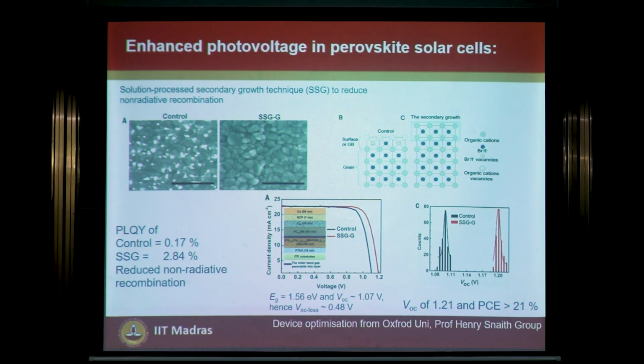Resistance is nothing but there are some charges which are getting non-radiatively decayed at the interface. It can be thermionic emission or heat, or it can just dissipate into the bulk. What we are trying to do is nullify those non-radiative decay channels. That is the main idea which we are doing. Because you said non-radiative decay, you are saying defect mediated non-radiative. Yes. And the simple measurement is the PLQE.